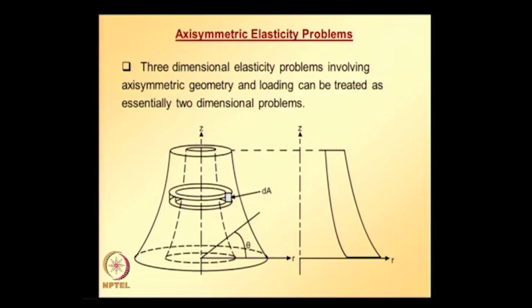So, for a 3-dimensional elasticity problem to be modeled as an axisymmetric problem, the structure, geometry, loading and material properties must be symmetric about the axis of revolution.